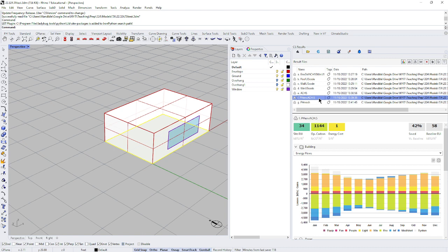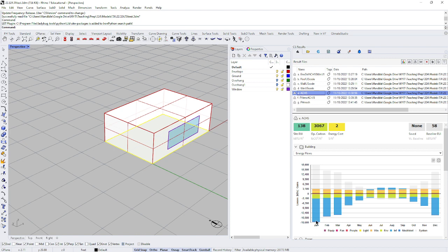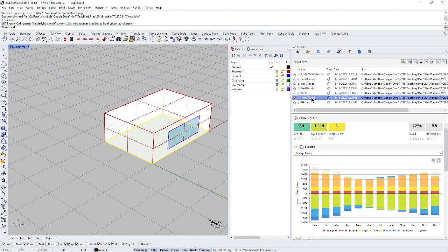And you see then we jump very far below our baseline. We're saving 42% of energy relative to the baseline. We're at 34 EUI. And now we're starting to get a lot more gradation here that we can see, because we don't have these ridiculous numbers, like our air leakage here is so high, which is this light blue, that we can't even really get much of a pixelation or resolution on the rest of these variables.